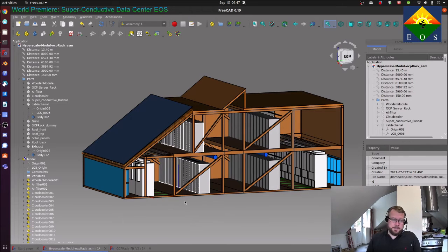And by eliminating AC in the complete data center, we don't have AC-DC rectifying, we don't have losses, we have a lossless busbar, we don't have losses in transport of energy, and we also don't have the power shelf itself, which is the last inefficiency standing within a data center, usually quite overlooked in the PUE analysis. We have managed to build this out quite nicely.